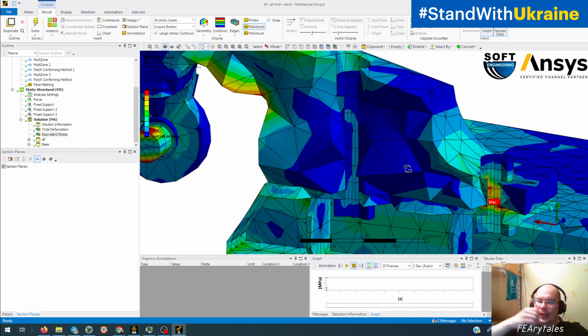So what we should understand from this effect: our mesh had a very big influence on the result. Sometimes you can obtain a much better result not by changing the size of the mesh, but by creating a more adequate mesh distribution.